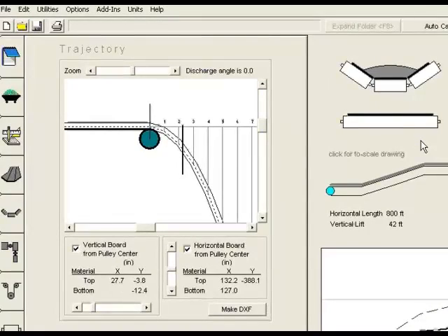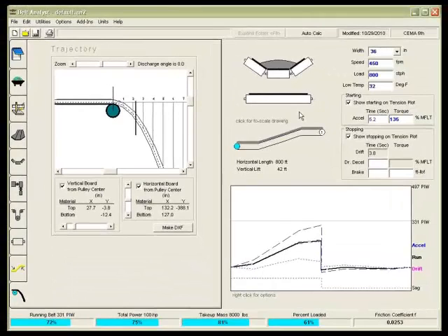So there we are. We have our conveyor fully input. I'd like to mention here that we have not designed this conveyor yet. We have basically just input the components. Once you input the components, the next step is to put it through its phases. Put this conveyor through its tests. Put it through, if it gets cold outside, what happens? If it changes the loading, as you would see what happens in real life in this conveyor, and go through your steps and see what turns red, what components need to change. You can do your what-if scenarios. If I change different componentry, what happens to the entire system? And the Belt Analyst will allow you to calculate all those changes, and you can run your tests.